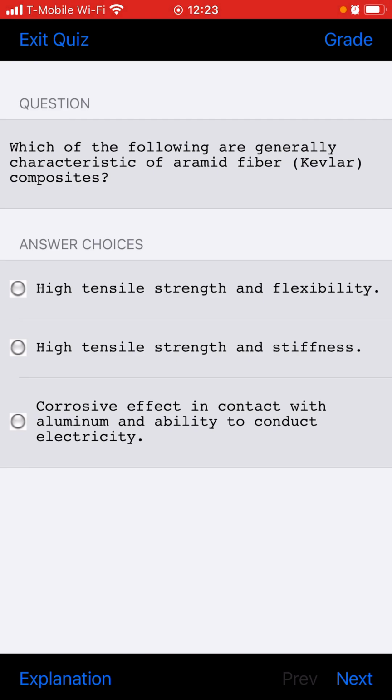When a piece of aluminum alloy is to be bent using minimum radius for the type and thickness of material, the layout should be made so that the bend will be 90 degrees to the grain of the sheet metal.